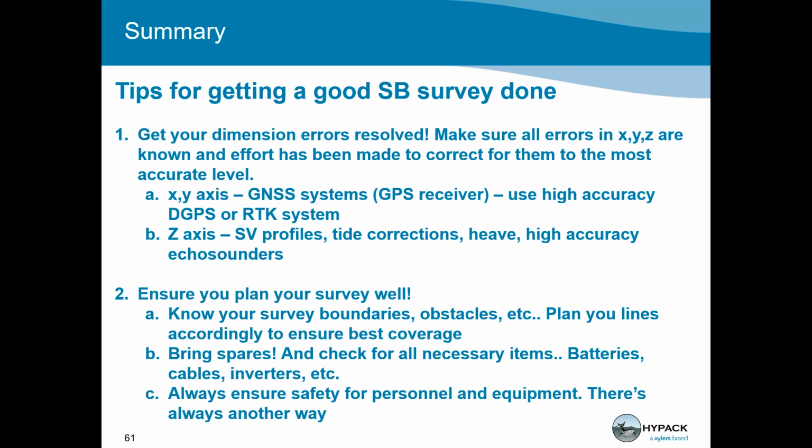The second point I would like to make is to ensure you plan your survey well. This is often said, but it's not practiced a lot. Doing things like pre-surveys, making sure you go beforehand to see where your obstacles are and what potential hazards you have, makes a big difference to your survey time.